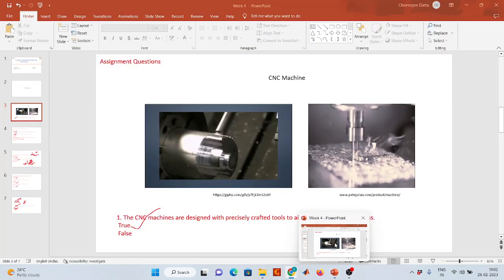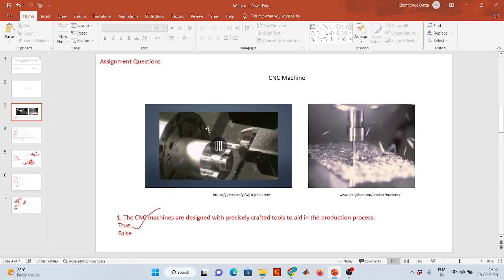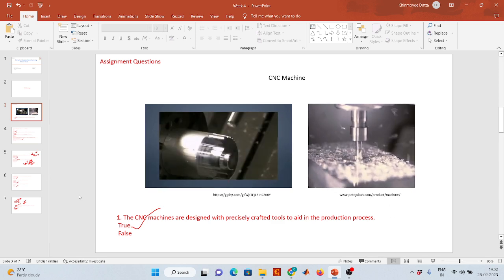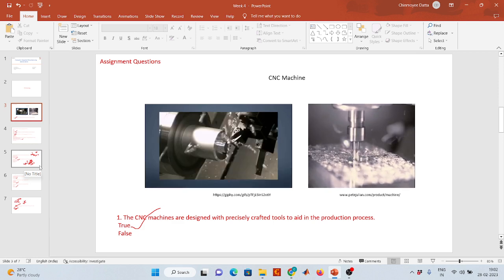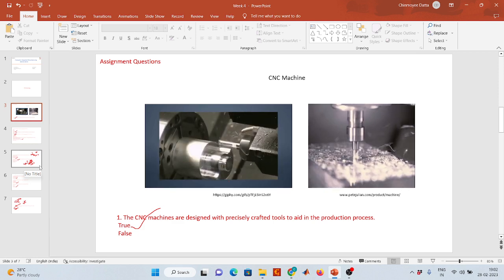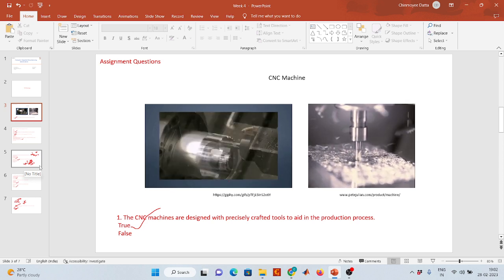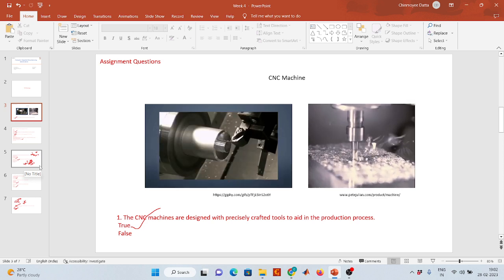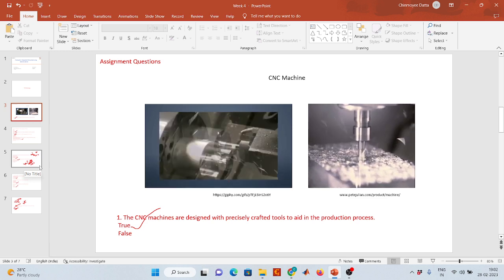Actually, while saying about the thermal conductivity and other things, you should have made a mention of coolant. Coolant takes away maximum heat actually. I didn't hear you saying that. Basically, when the cutting happens, in some cases it will be submerged. For example, if you look at the titanium,